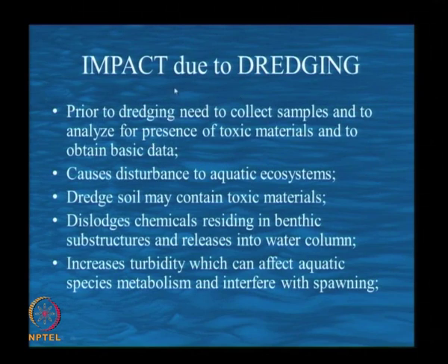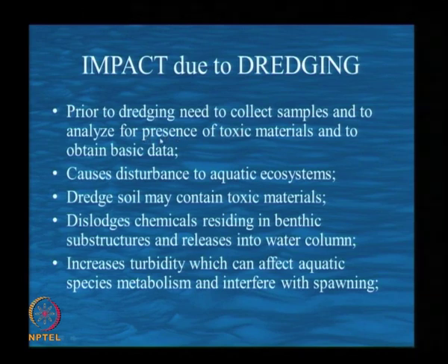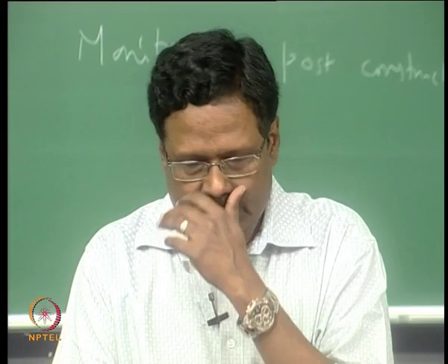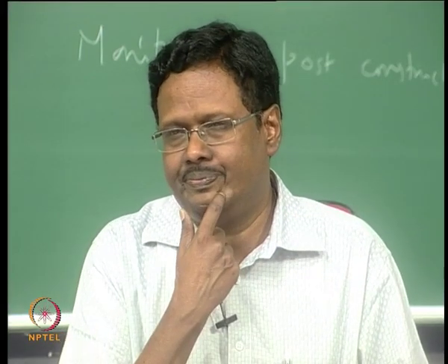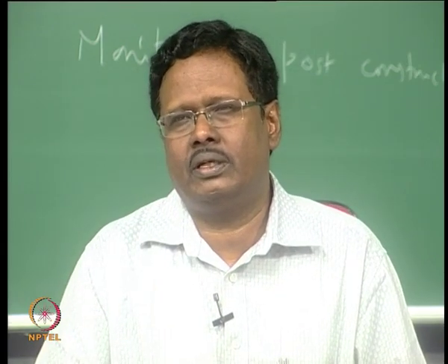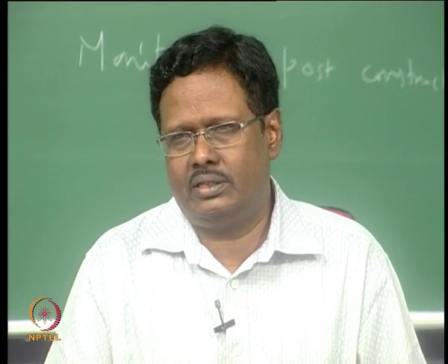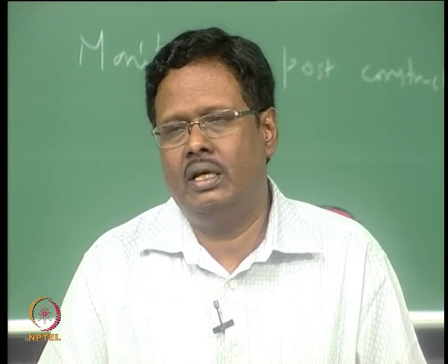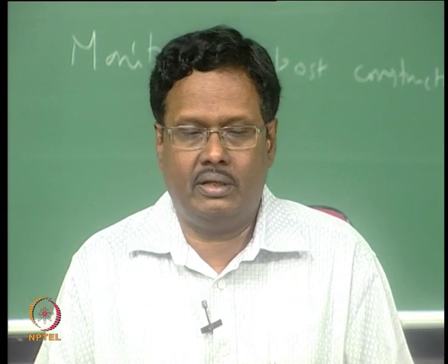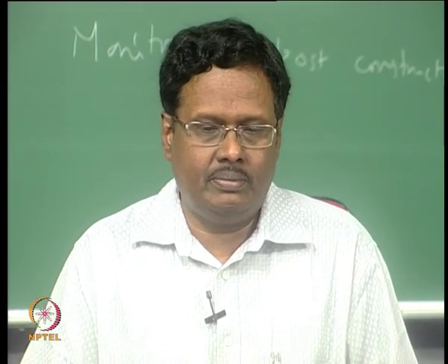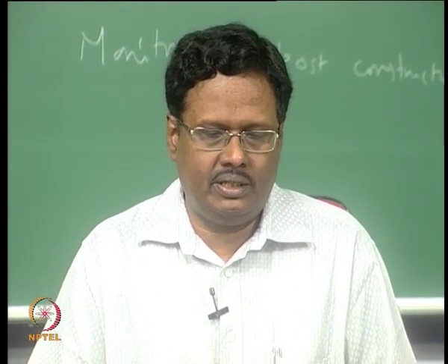Before dredging we have to take samples and analyze them for the presence of toxic materials and obtain basic data. This is very important. Suppose there are some toxic materials, you cannot dump them on the shore. Northern side we are putting 2 million cubic meter. If there are toxic materials, you do not dump them on the northern side; you can either dispose of them into the sea, or you have to have a separate place where you can dump this toxic material. So, you have to study the sample for that.